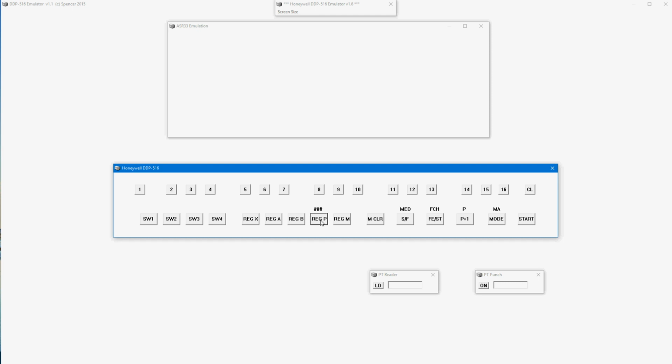If we're in the program counter, we put 0, which we've done by doing master clear, and set fetch and P+1 in memory access mode, then when I press start into the M register, we will see the contents of location 1. And it says 010057, which is the first instruction of the key-in loader. And then the next one, 030001, which is the input-output OCP command to start the high-speed paper tape reader, and so on through the key-in loader.